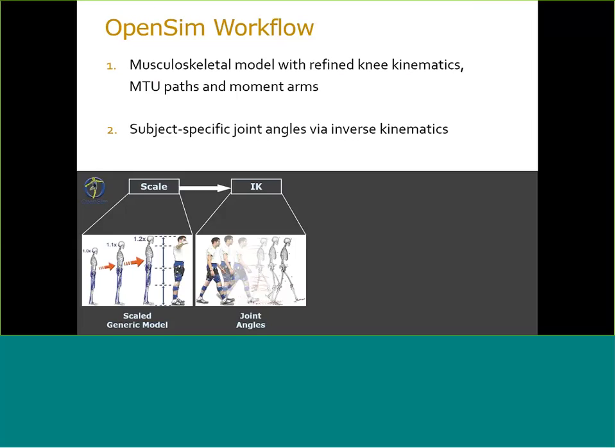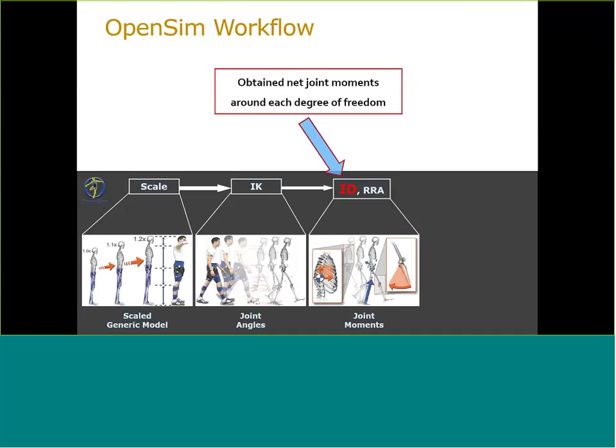Thanks, Allison. So at this point, we had a model that had refined knee kinematics and more experimentally consistent muscle tendon unit paths and moment arms. We also had accurate joint angles from inverse kinematics and all the tweaks that we made with our virtual model markers. So we were now ready to generate some muscle-driven simulations of pedaling. To do so, we followed the standard OpenSim workflow to generate muscle-driven simulations.